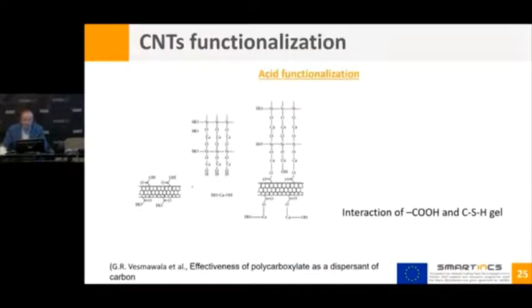As I was mentioning, here you have the carbon nanotube that was functionalized, with these COOH groups laterally fixed onto the carbon nanotube, and of course this will favor the growth of the cementitious hydration products that form after the addition of water onto the cement powder. And of course you will have a strong binding of the carbon nanotube to the matrix, and this will increase the mechanical strength of the cementitious system.